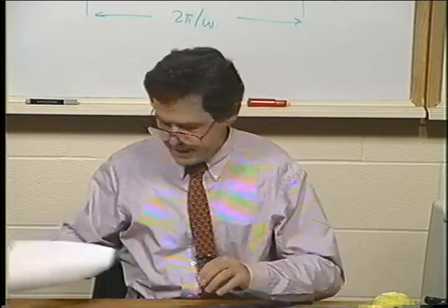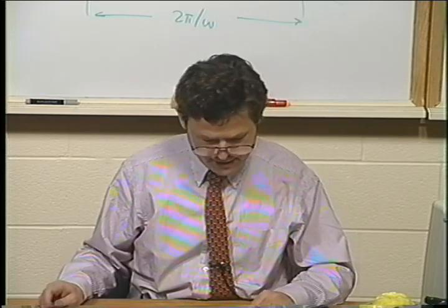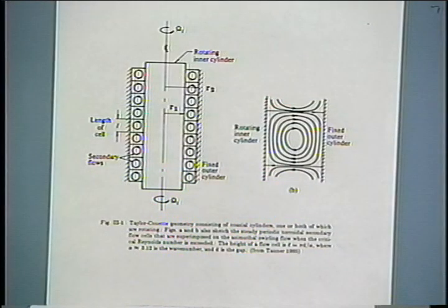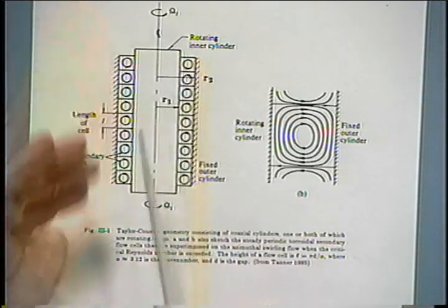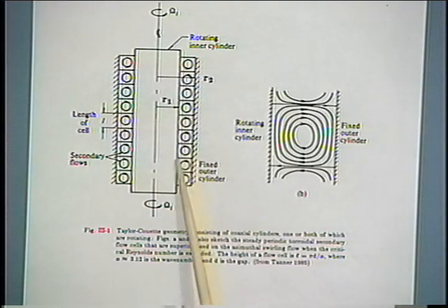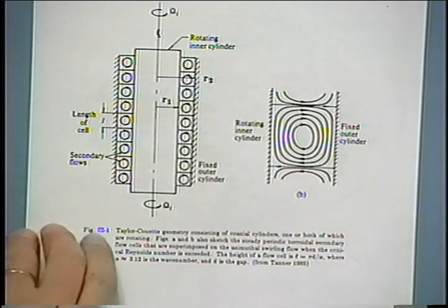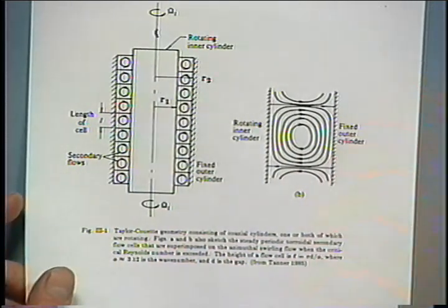There are other instabilities coming in, typical Taylor-Couette instabilities, which are known for Newtonian liquids if you have a rotating cylinder in a stationary outer cylinder or vice versa. Then you have some zones which are rotating, and elasticity changes the onset of those and the direction of those vortices in the same way.